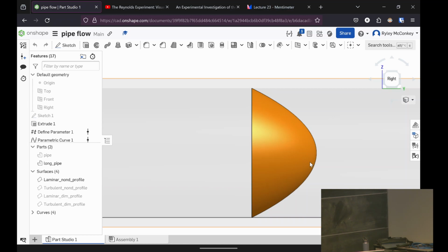The relevant thing for pipes is the internal diameter, right? Because that's the diameter that the fluid actually sees as it flows through this pipe. So this is going to be a confusing part of your project for a lot of you, but often when people say a diameter of a pipe, that might not actually refer to the internal diameter. But it's really easy to go look up on Wikipedia.